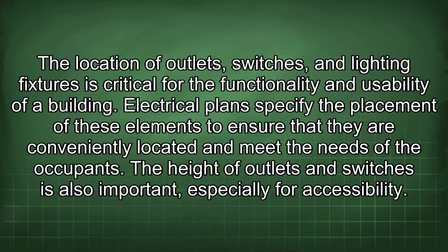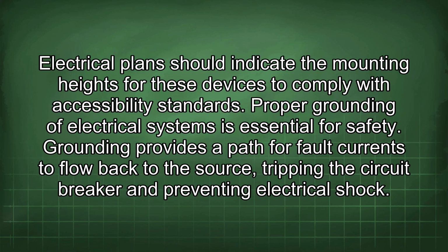Electrical plans specify the placement of these elements to ensure that they are conveniently located and meet the needs of the occupants. The height of outlets and switches is also important, especially for accessibility. Electrical plans should indicate the mounting heights for these devices to comply with accessibility standards.